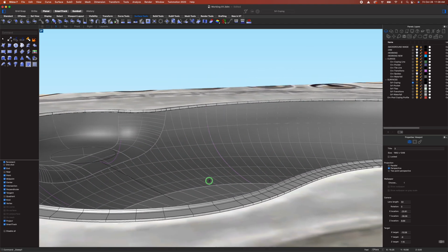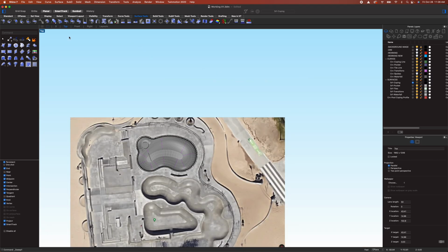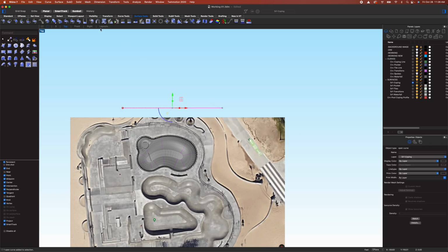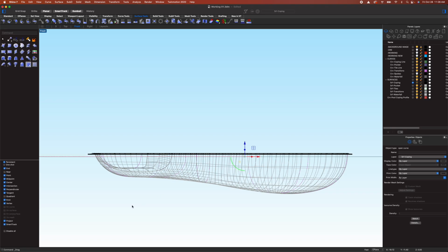Let's go one step further, and let's add a tile line. So if we were to just draw a line, and then go to our front view, let's move this line down a half a foot, which is 6 inches. And that's pretty appropriate for a tile line. And we'll just select our volume here, type in split, and select the line we just drew as our cutting object.